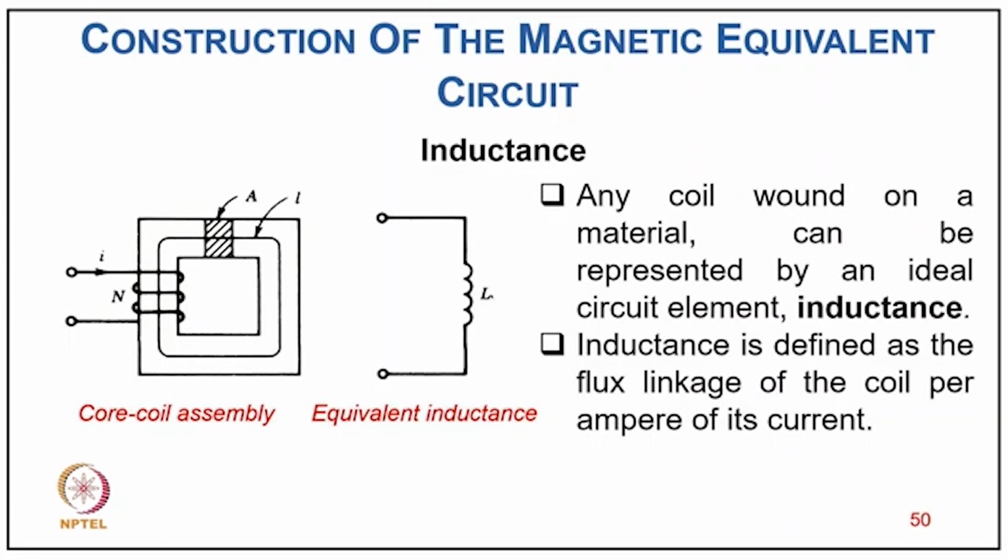Usually we put this small air gap in the inductor so that the value of inductance does not change even if there is saturation in the core, because the majority of the MMF is consumed by the air gap. Depending upon the relative permeability, the ferromagnetic material consumes very small excitation and the major excitation is in the air gap. So even with saturation, the excitation requirement of the ferromagnetic material may not change much. So we use this for inductors, even in DC circuits as well as AC circuits. That is the basic concept of how we design the inductor for many circuits.